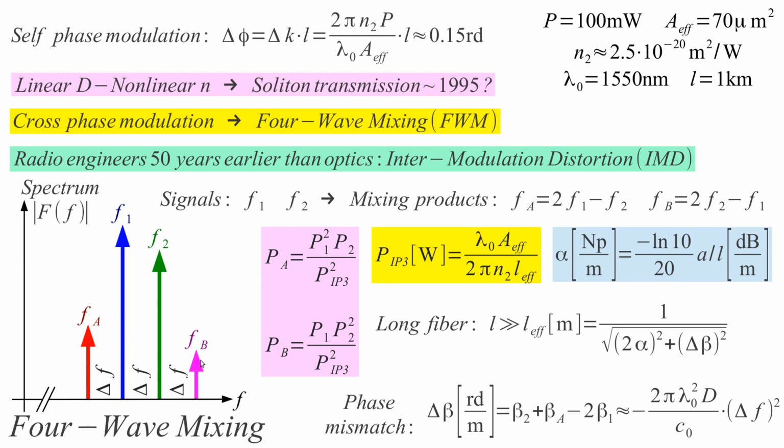And these additional signals may fall on other frequencies in use by other communication on other channels on a huge wavelength division multiplex on a transoceanic cable. So this is real interference. They cause real interference. How does four-wave mixing happen? Well, intermodulation distortion is a much better term.